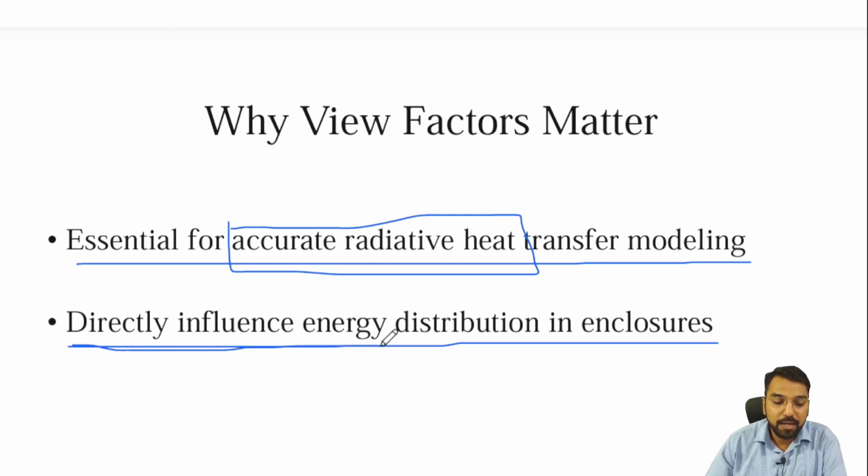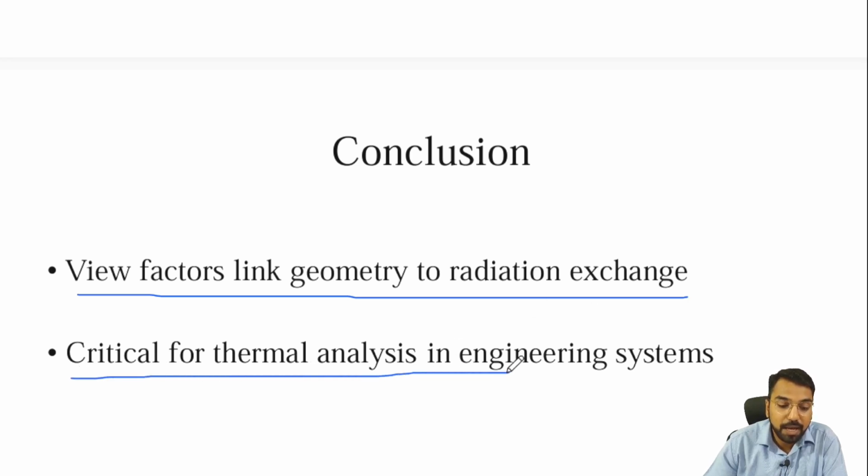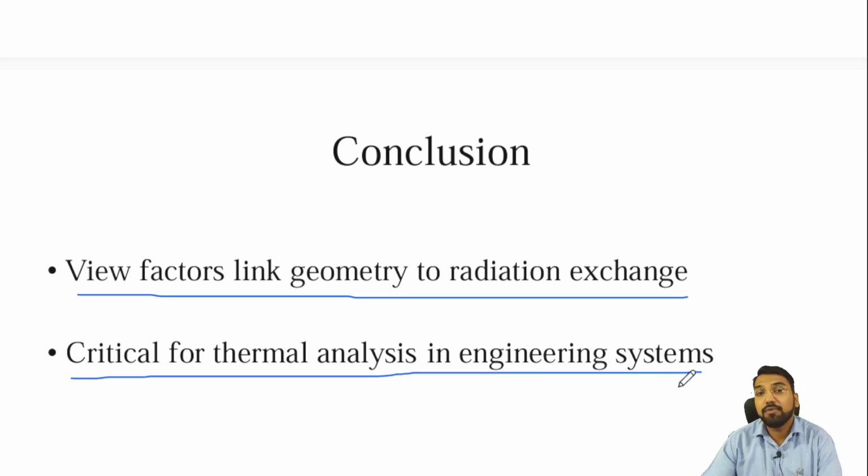So directly influencing the energy distribution in enclosures. How much energy I want to transfer from one surface to another, or how much energy I want to restrict from transferring as radiation, is mainly dependent on the view factor. So what is the conclusion of today's lecture? The view factor links the geometry to the radiation heat exchange, the fraction of heat transferring by radiation, and it is critical for thermal analysis in engineering systems. It is a very critical thing.